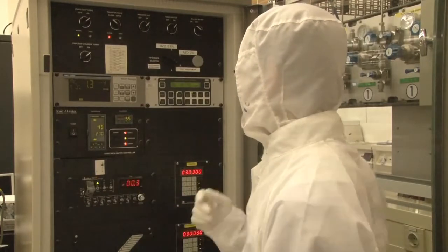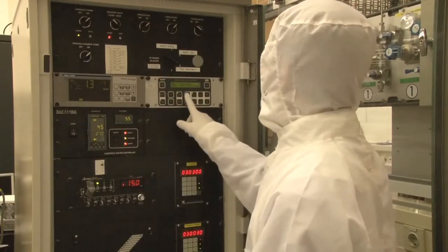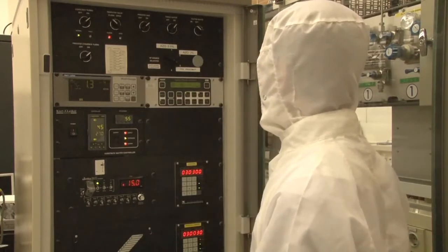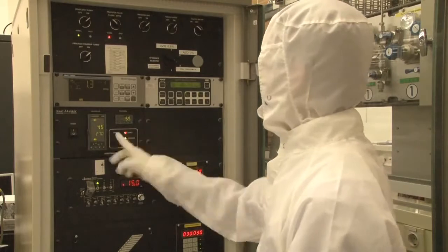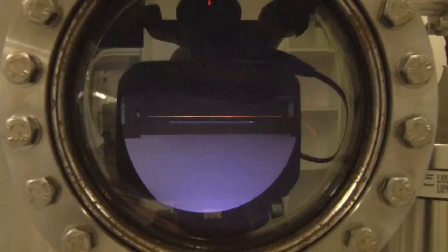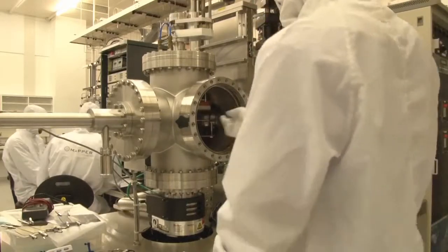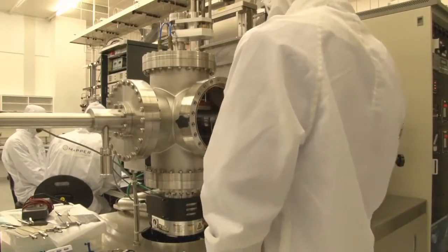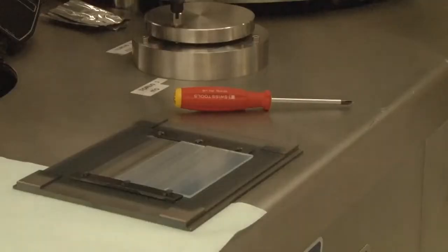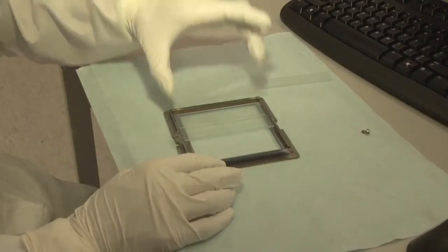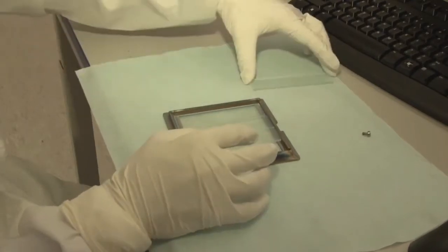During sputtering, the zinc oxide target is bombarded using an ionized noble gas like argon. The generated aluminum zinc oxide species are sputtered into the chamber and deposited onto the substrate. Here you see the sputtering plasma. After the sputtering processing step, we have a glass plate with tin oxide and on top a very thin zinc oxide layer. Next, the samples are mounted into a different substrate holder.